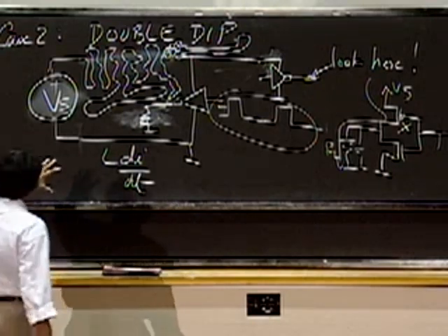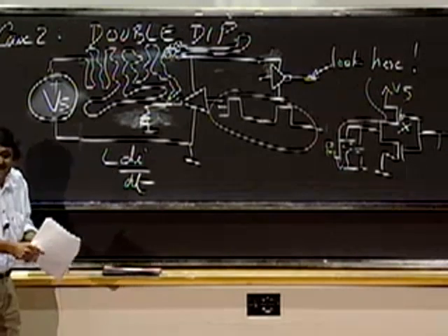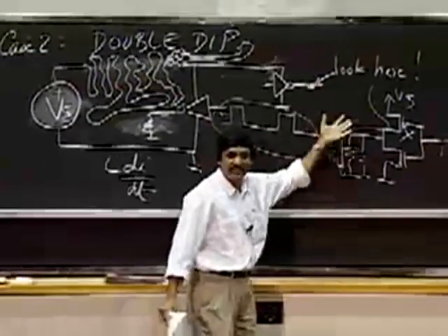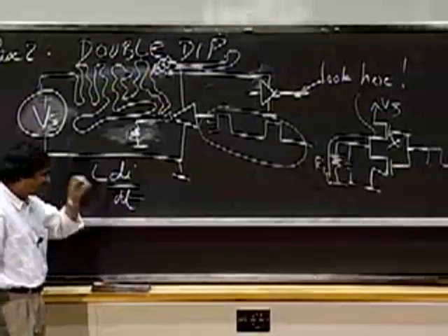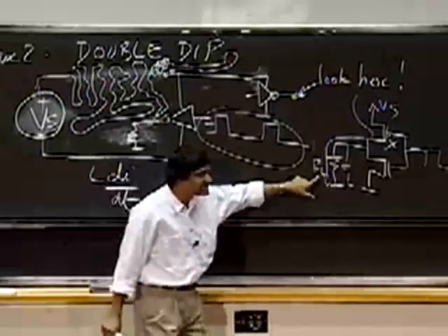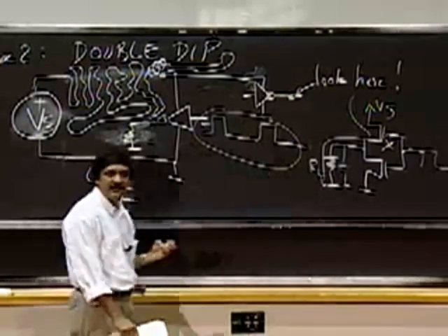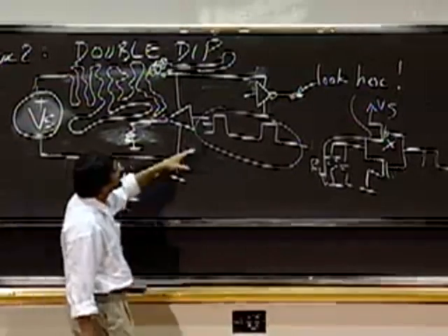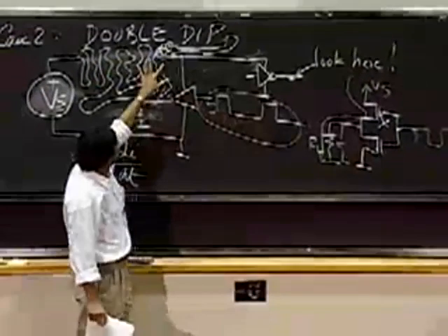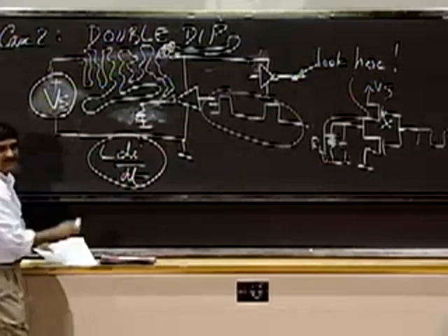For an inductor, the voltage across the inductor is L di/dt. So if I'm switching a large current through the inductor every cycle, big di/dt, di/dt is large. I made it large by having a very small RL. So I'm pulling a big current through every cycle, and then stopping it. And therefore, I'm getting these big drops across this inductor that relate to L di/dt.